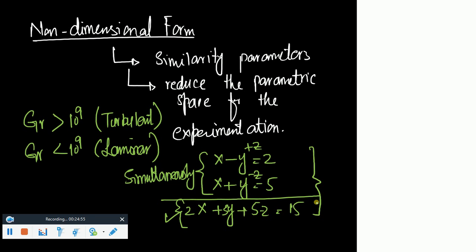You understood that? So that's why, if some of you have used Fluent or CFX for any kind of simulation, or if you are having a course on Fluent in the next semester or the one after, you would see that once you select the flow to be incompressible, it would ask you whether you want to solve the energy equation or not, right? If you do not want to solve the energy equation, you would keep the box unchecked.